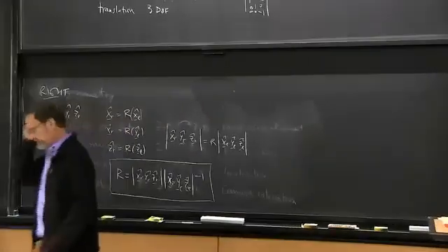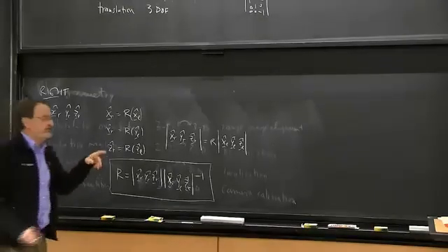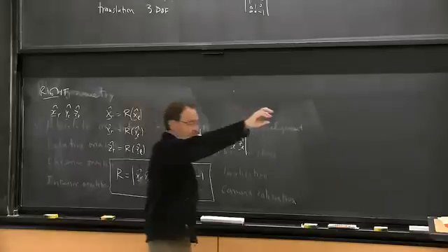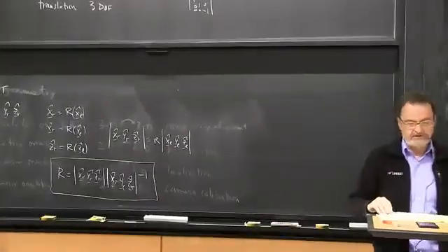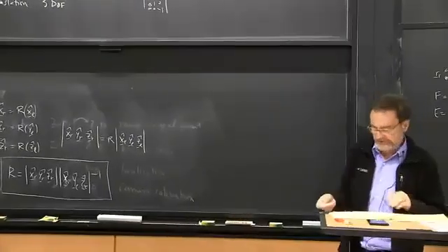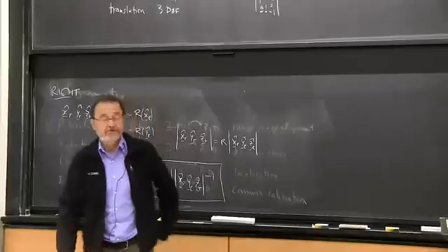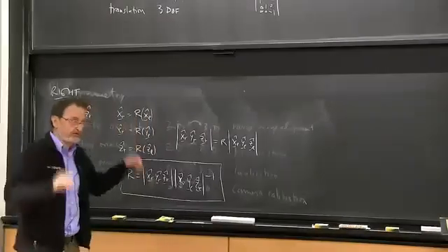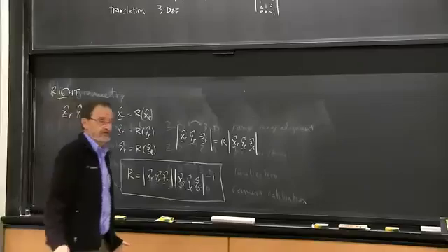We said that if we remove translation for the moment, we have 3 degrees of freedom left to find. And then we said, okay, we have 3 correspondences between the 2 coordinate systems. So that sounds about right. 3 constraints, 3 unknowns. But those constraints are much more powerful because they're not just scalar equals a scalar, they're vector equals a vector. So each of them is worth 3 points. So we actually have 9 constraints.